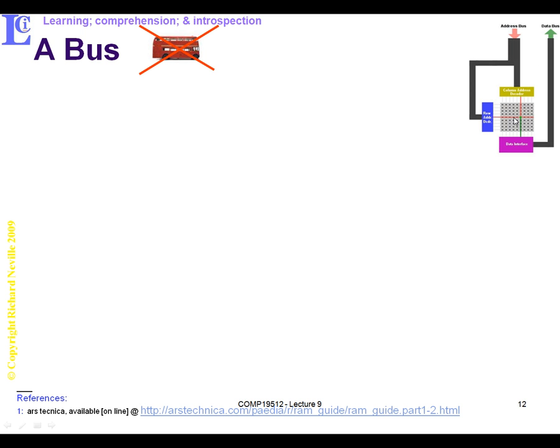This is really what a memory does if it's a DRAM. What it actually does is it takes in the address and splits it in half, basically, into two separate addresses, and then it does a column address scan and a row address scan, and that's where we get the idea of CAS and RAS, row address and column address, which gives you a particular memory location in the memory, and this is either read off or written into once this memory location has been set up. Now that's the technical detail, which is a bit beyond the scope of the course.